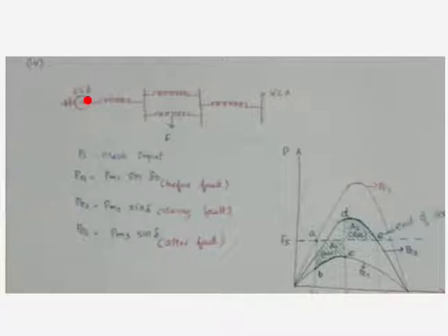So in the first case, it is these two in parallel, in series with these two. Then a fault happens over here. So this will become a delta, which we have to convert into a star, and that star will be in combination with these two. Then you have to convert it into delta. That conversion we will see. That is another network condition, which is a reduced network condition. And finally, when the fault is cleared, this transmission line goes away. So it is going to be just these three in series.